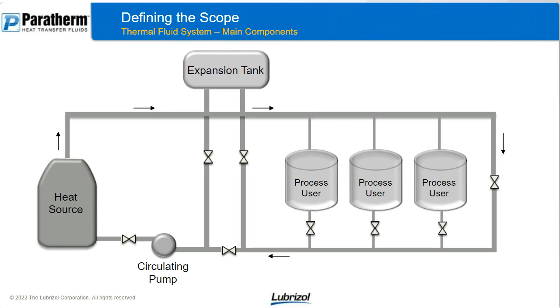So getting a little bit more into what we mean by closed-loop system and talking about the main components of a thermal fluid system, let's start off by talking about your heat source. Your heat source could also be a cooling source if you're talking about cooling, but focusing on the high temp, we're going to be mostly talking about heat source. So that could be a fuel-fired heater, an electrically fired heater, or a waste heat recovery type system. Whatever the main heat source that's supplying the energy to the fluid, the heater of the system is going to be the main area of focus.